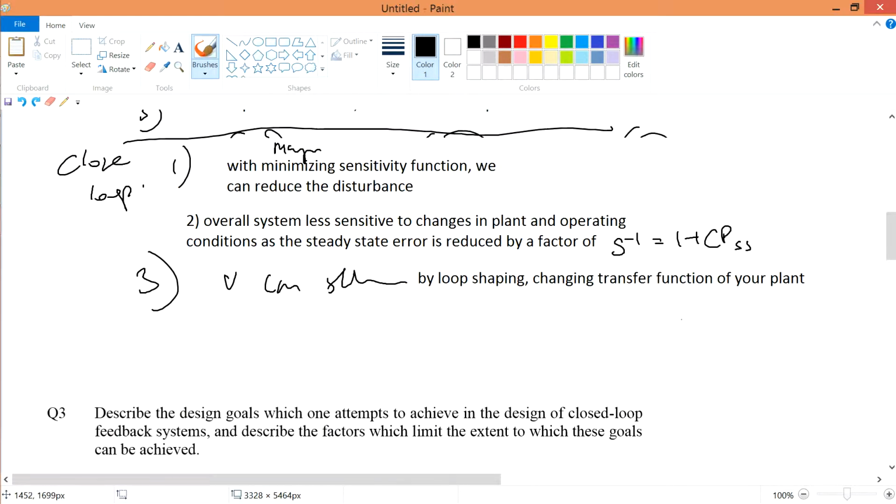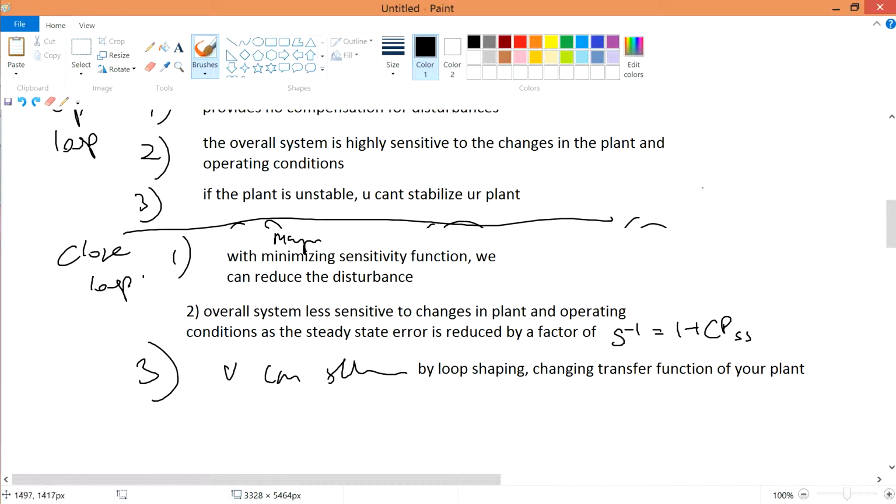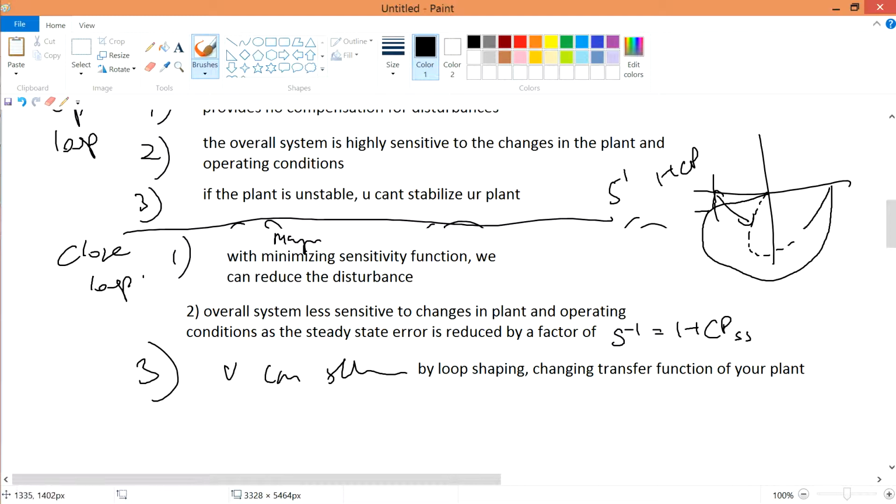In the last video, we talked about the proper and the improper system, right? And therefore, if your Nyquist plot is very near to -1, then you can loop shape. You can change your controller a little bit and alter it, and eventually it will go to here now, somewhat safer, in a safer zone. And in order to measure, we measure using the vector margin, the 1 plus Cp, or S minus 1 in this case.